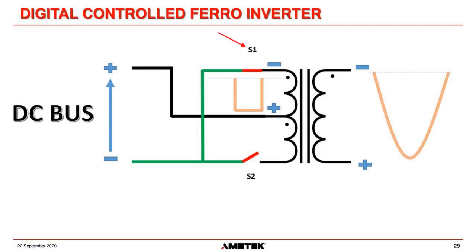So in this bridge, the DC comes into the center tap of a transformer, and we turn S1 on. And so we drop the full DC voltage across the center tap to the end. And you may notice I show some dots on this transformer, and these dots are the polarity. So when we look at the primary, you see a plus to minus across the primary, and the secondary is in phase with the dot at the top of the primary. So that's why we show a negative half cycle coming out of the secondary.